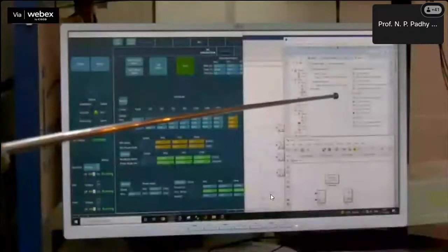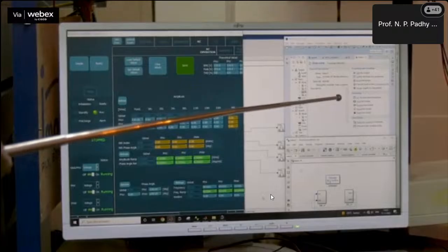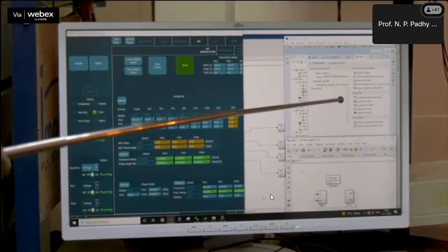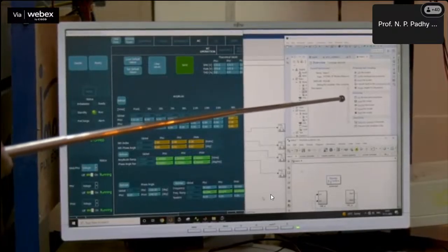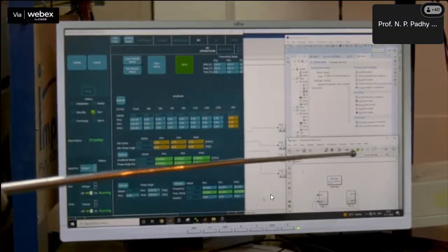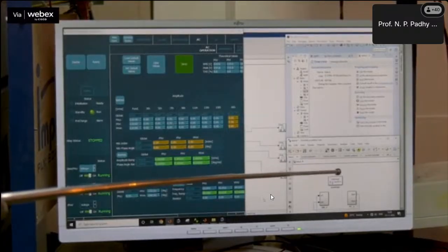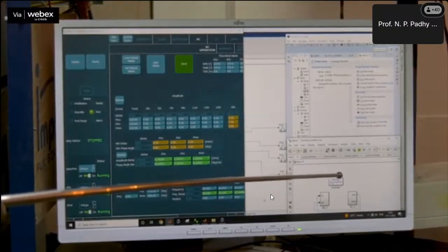The DC microgrid is implemented in the Opal RT, which runs on RTLab software by calling the MATLAB Simulink files. The DC microgrid consists of solar, BESS and variable DC load connected to a DC bus.